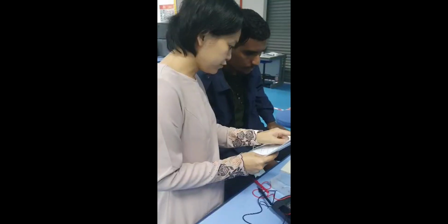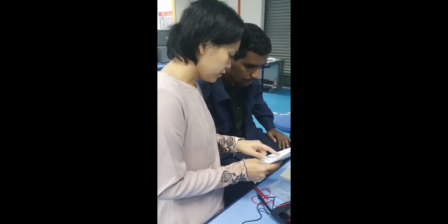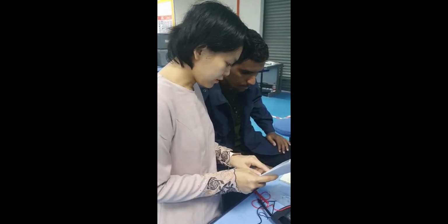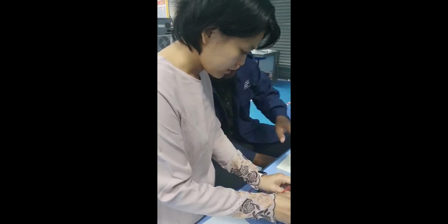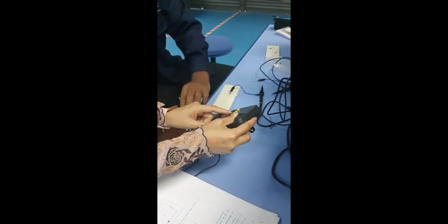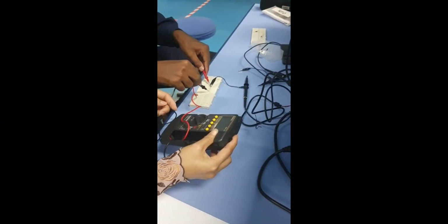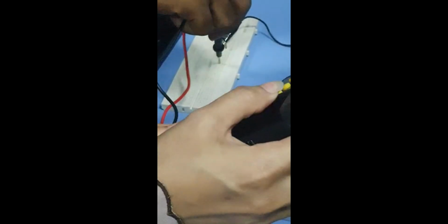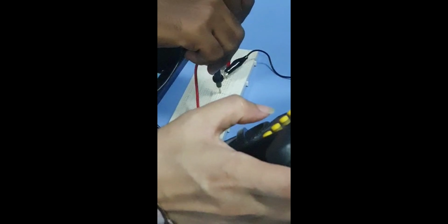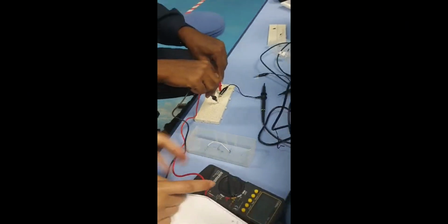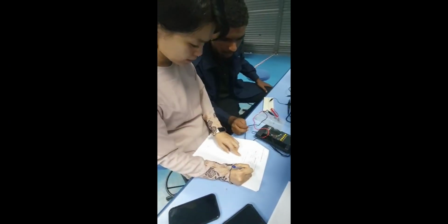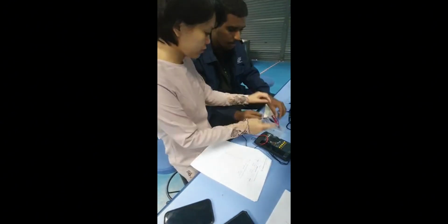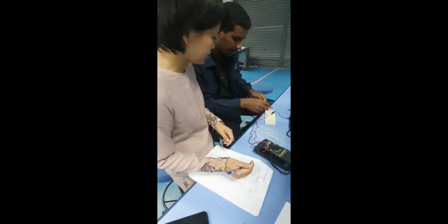First, you have to check the condition of the diode. So follow this one. This is the multimeter, and this one is the diode setting. First you turn this one to the diode, and then you put your leads on the anode and cathode. So you read the reading. Okay, 0.8, so you have to record here. Anode to cathode, 0.8. Then cathode to anode, the opposite. Turn it.